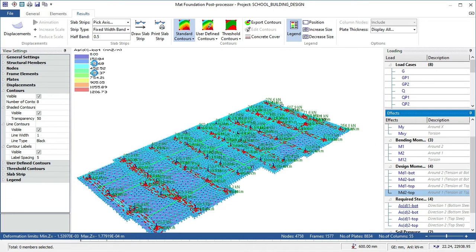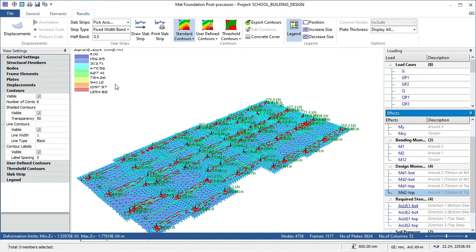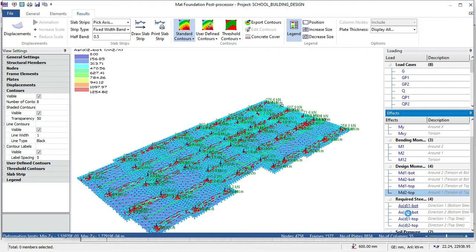Now if you check your slab reinforcement table, which I believe you should have, you can relate what spacing of reinforcement and what size of reinforcement you will use. Although, because we have already cut strip before we get to this stage, I will show you how to see that reinforcement. Okay, so right now I'll click on the top one, because I've already clicked on the MD2 button, as you can see there. So I'll click on now.